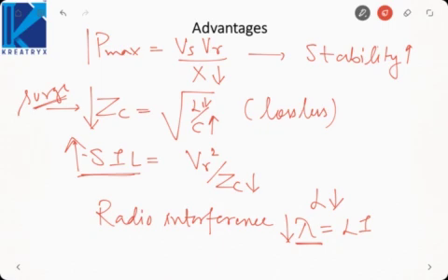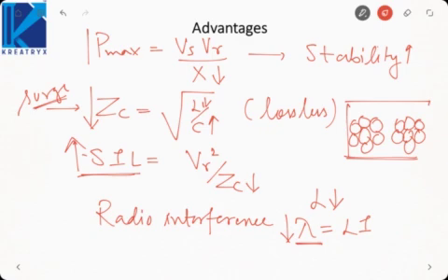So inside a bundled conductor, if there are two conductors, each conductor will be stranded. Do not think that each is solid. So like this grouping will be there. Each is a stranded conductor, and these two conductors are collectively called as bundled conductor. So stranded conductor is not eliminated, but rather it becomes a part of bundled conductors.